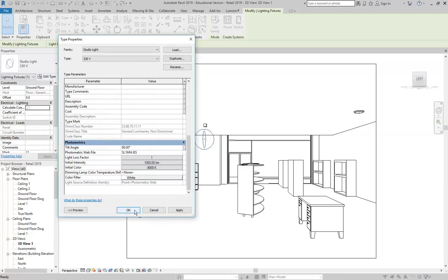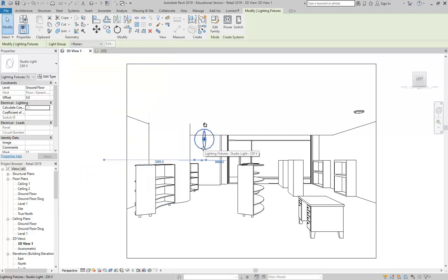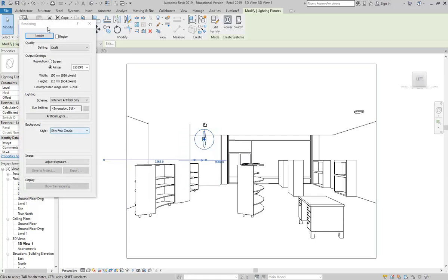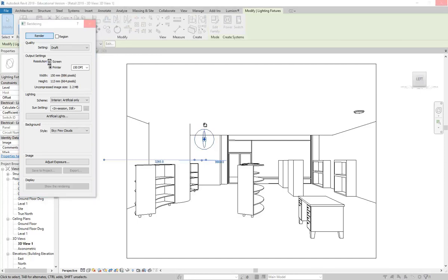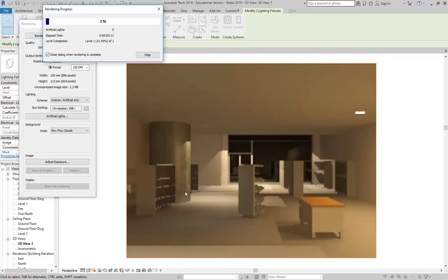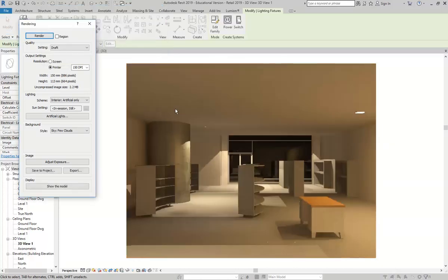Okay, so 1,000 lumens, again, is a good baseline to remember. And you don't want to go too much above or below that level. For a really dim LED light, you might go down to even 10 or 20 lumens. But for something that's going to really give you some sort of lighting onto other things, you'd need it to be at least in the hundreds. But if you're going the other way, above 1,000, if you're getting into values of more than about 3,000 or 4,000, then your lights are probably too bright, and you probably should be looking at exposure to adjust your overall brightness instead.